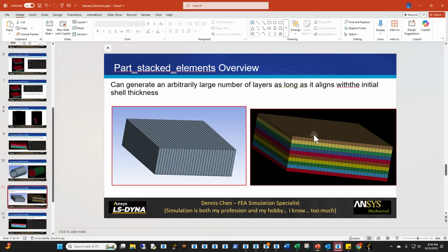Make sure the thickness corresponds to the overall thickness. Then just assign the thickness to each layer, assign the material to each layer, assign a section, assign an hourglass. And you will have a full stack that allows you to do other analysis with, and it's all no merged, very cleanly done. It makes the job cheaper to run. It's also extremely efficient in terms of getting the model to solve quickly.